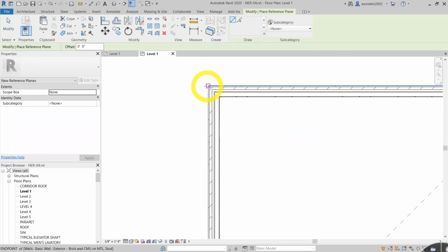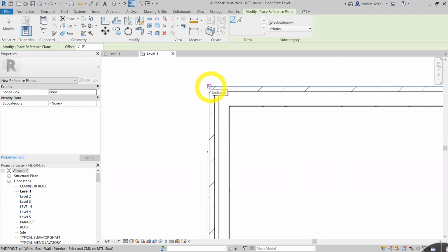Let's go way in here. And let's pick this. Okay, and I'm also going to make one, say 1 feet 6 inches. Flip, spacebar, 1 feet 6 inches from this spot. Okay, that's where my first window, I'm just making a nice solid base because I know that's where I want my first window to be dimensioned from. So that's why we're making this reference plane.